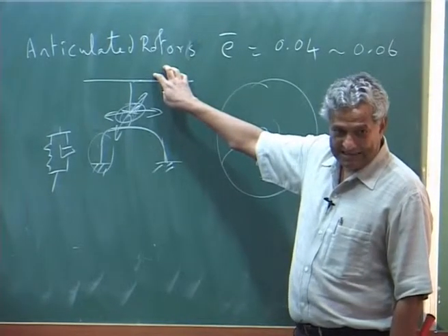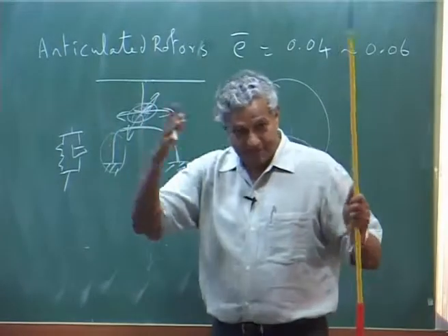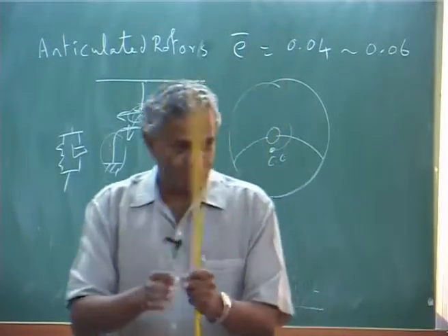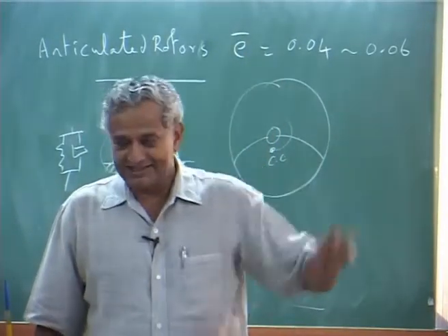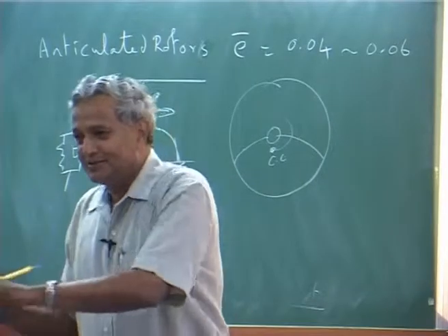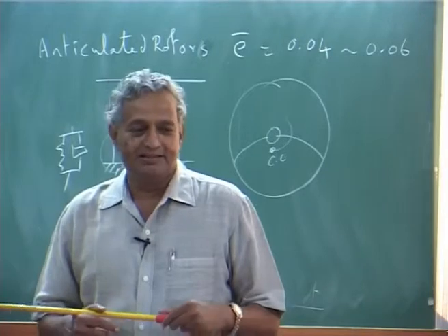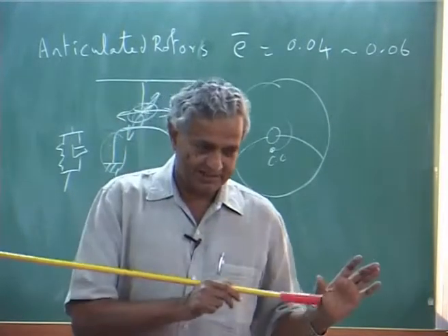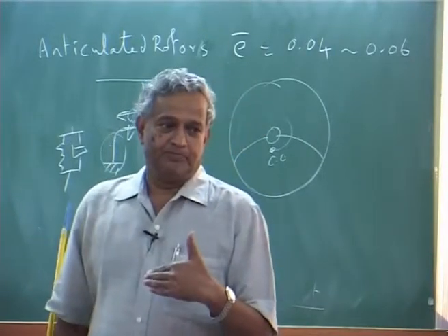Each blade will be rotating, so you have to have each blade's equations, and they are affected by fuselage motion. So usually a transformation is done from rotating frame to non-rotating frame. That transformation is called the multi-blade coordinate transformation, a mathematical transformation, to get it into fixed frame mode.